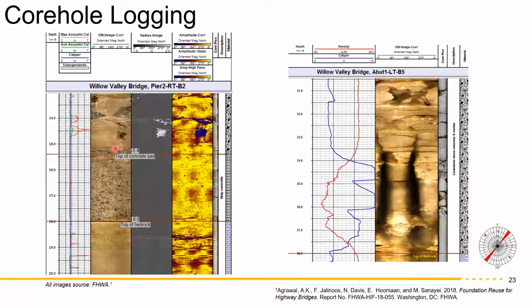It also has a 3-component accelerometer to correct for inclination. So what you have is an oriented core, and you can look at it in 360 degrees. Just open it up like this, so you can see the whole borehole contact information fully oriented, and then you can get the strikes and dips of any feature that you want to take a look at.